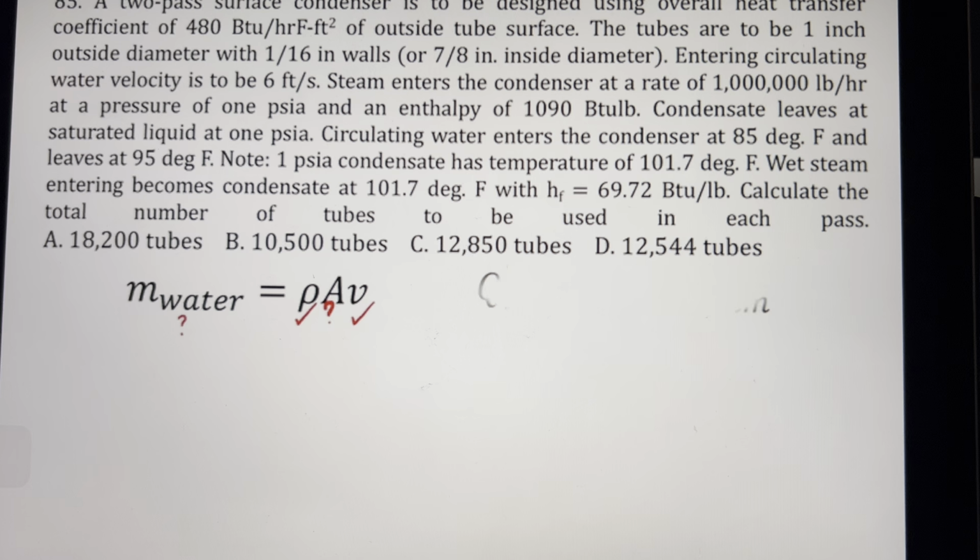So in formula form, the heat absorbed by the water is equal to the heat rejected by the steam. So the mass of water is inside the heat absorbed by the water because there is an increase in temperature of water. So we will be using the sensible heat formula. Okay, for the heat absorbed by the water, that will be mCp del T, where m is the mass of water. So let's identify first the mass of the water.